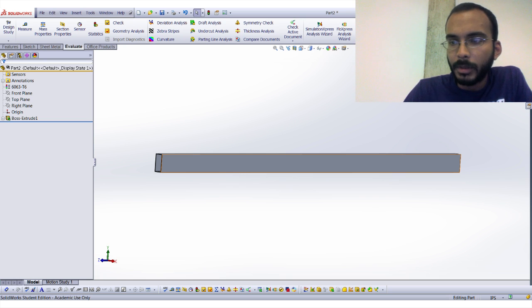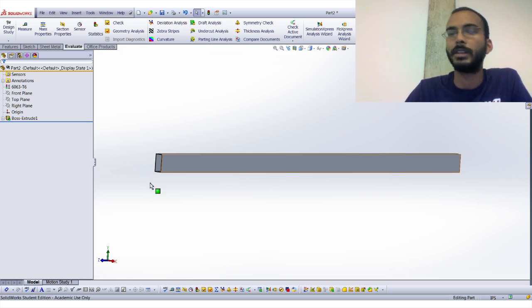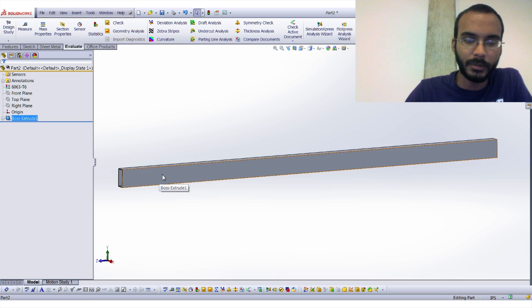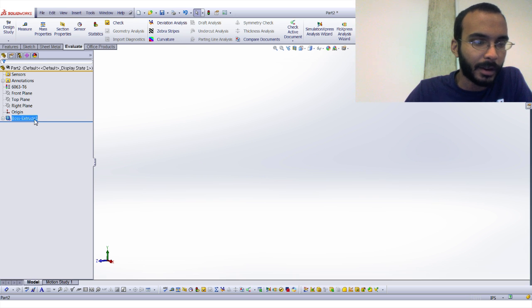All right, so now that we've sketched, it doesn't really matter where you do this, if you have just a plain rectangle or if you have something like I have, it doesn't really matter. But if you right-click on one of those faces, it'll bring up your full right-click menu, which is where you can also start getting acquainted with as well. So SolidWorks likes to prevent you from having to move your mouse all the way to the top sometimes, so it gives you kind of suggested items here. So you can hide and show it, so if you want it to go away, you can hide it, now it's gone. Then you have to come back over here and hit the glasses again to show it.